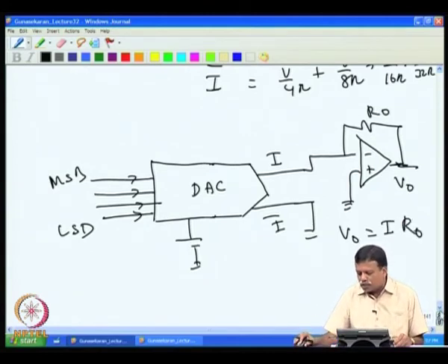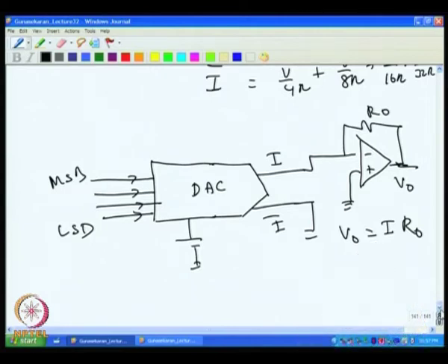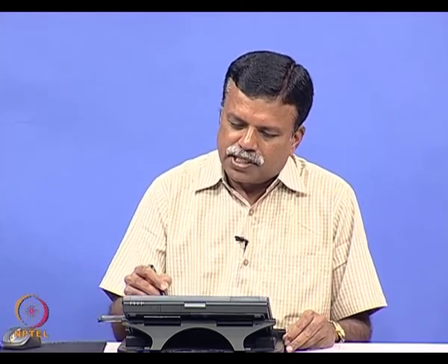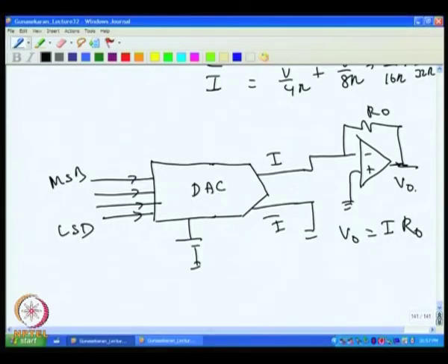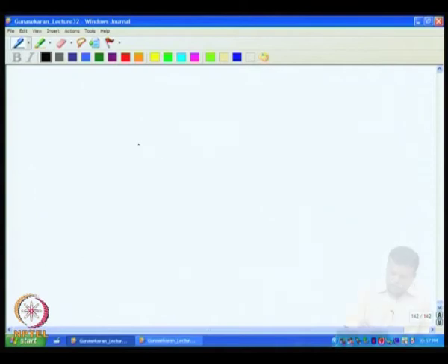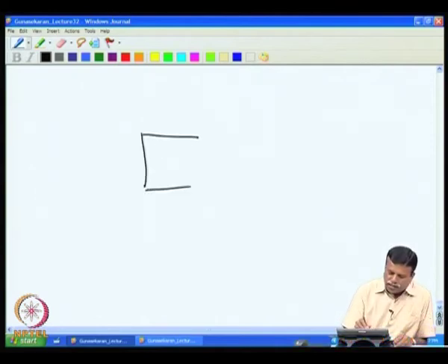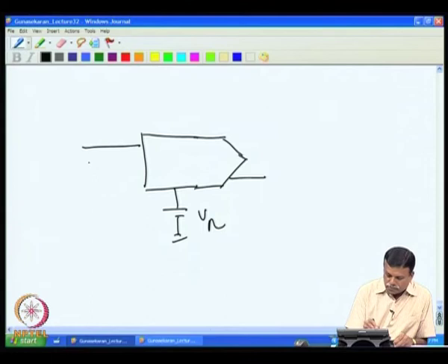We can also use the minus input, and we will see various applications of how the minus input is useful. There are applications where we use both plus and minus, and applications where we use only minus, and invariably plus is utilized. Here the output voltage is actually minus, and it can also be made a DAC with current sinking. That is another popular DAC which is available. We will have another type, where we have a V reference given here and then a digital input.